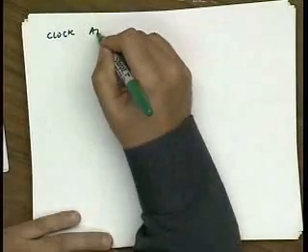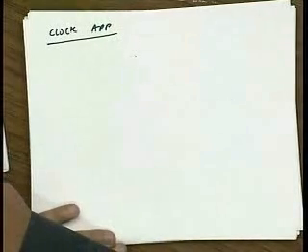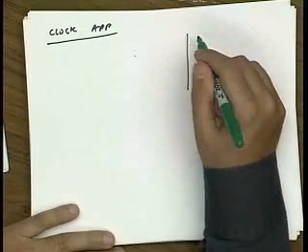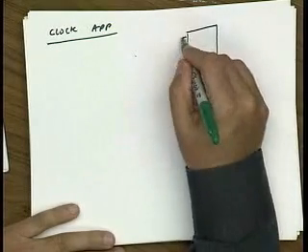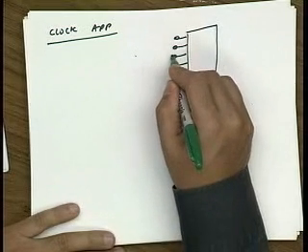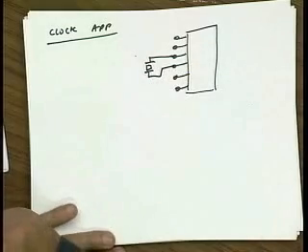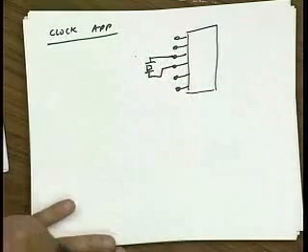A couple lectures back, we talked about clock drivers. Almost all circuits need a timing reference. So if you have a microprocessor or high-speed logic circuit, you need a good clock. Often you'll come off chip to connect to a crystal, let's say like this, and this is your clock reference.